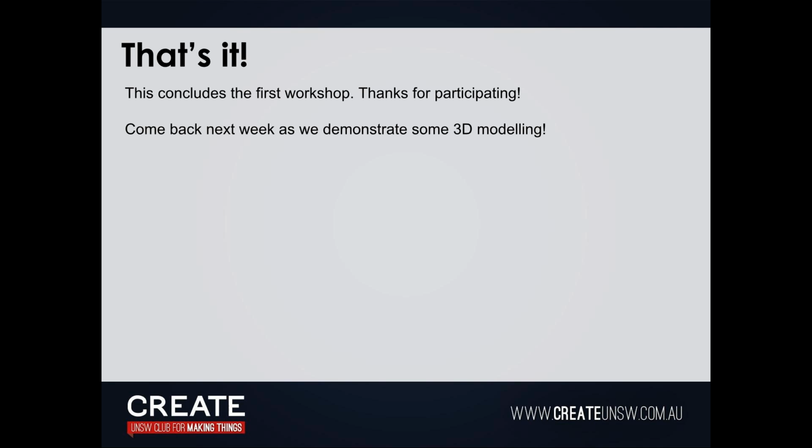There's a lot of things, but if you're not sure about how much the 3D printer is shrinking, you just print a really small cube and then you measure the actual dimension against what you put in there, and then you just divide that. You find the 2 dimensions and you divide that, and then you find the midpoint. It's basic math, and then you just calculate that as a percentage. You go back into your 3D printer's slicing software. So if it shrinks by 1% or just 1.01, it's pretty good.